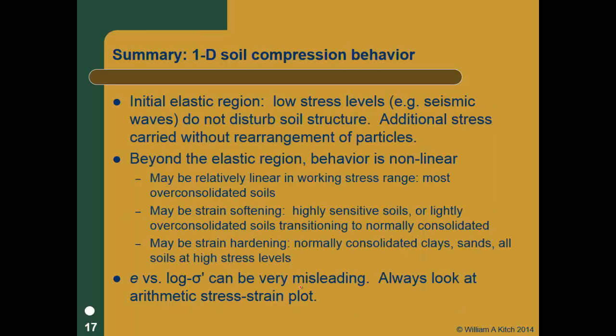Sorry. So here's my summary. For a lot of soils, you'll have an elastic region down at the toe, at the very bottom of the stress-strain curve. This is the level of strains you get, for instance, in seismic surveys or in propagation of earthquake loads. Those are very, very small strains and very, very low stresses. So that's definitely true.